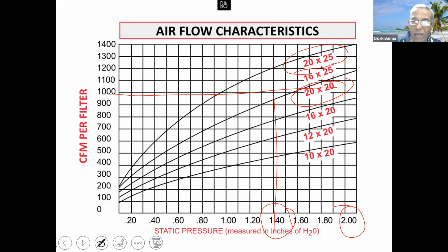So the exhaust duct has to be very clearly negative pressure. It has to be strong enough to withstand that negative pressure and take care of it. So it's very important. And that is where a minimum gauge of GI sheet or aluminum sheet is to be used, or maybe stainless steel sheet is to be used for exhaust ducts. So that has to be catered for.